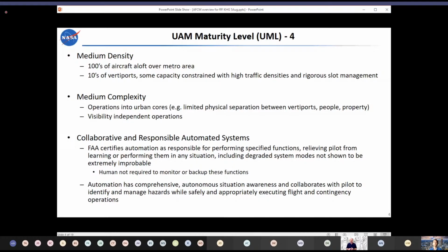Traditional automation, there's a lot of benefit in terms of safety, performance, in terms of things like low flight technical error combined with workload relief for the crew, but almost all of the automation functions on the flight deck of a commercial aircraft are allowed to fail, and the pilots are expected to be able to complete that mission using traditional piloting skills.